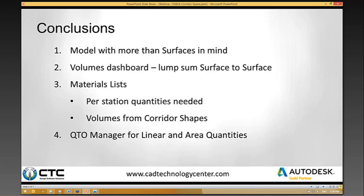I mostly focused on corridors today, but another great place for it is pipe networks. You can program that stuff right into your parts list. And then you can also use it to reference anything else, like survey figures was brought up, feature lines, polylines, AutoCAD blocks, you name it. Any type of AutoCAD or Civil 3D object, you can pull data out of it. And I didn't even quite get to it, but there's an option to put in formulas there. So if you want to take what's an area quantity and convert it to perhaps tonnage of asphalt, you can do that as well.